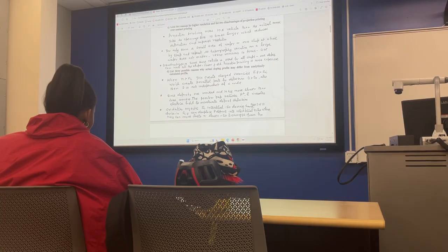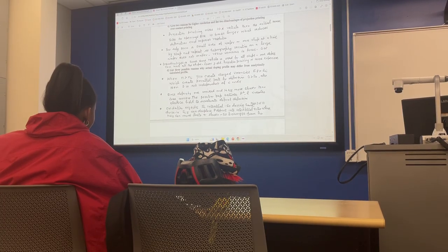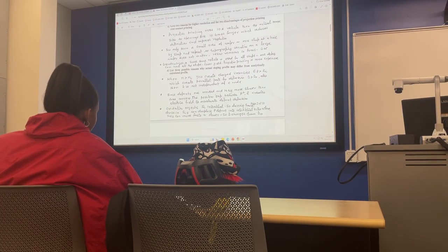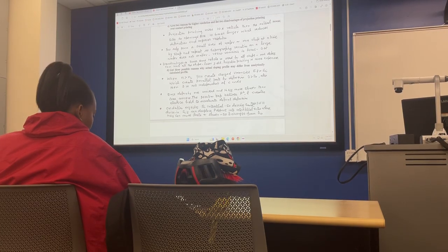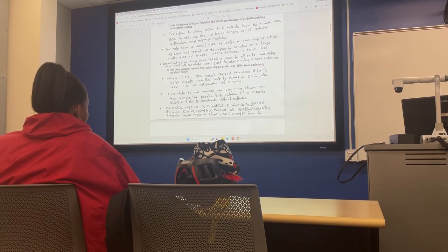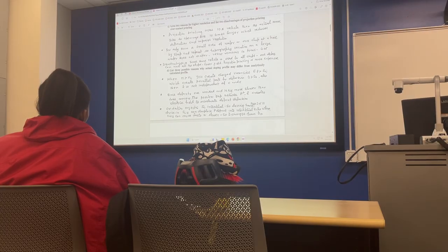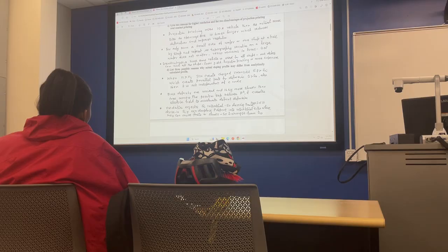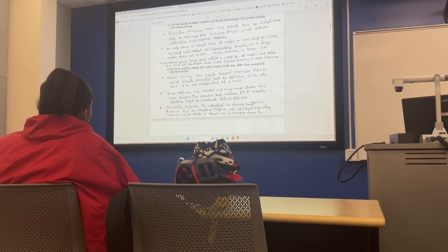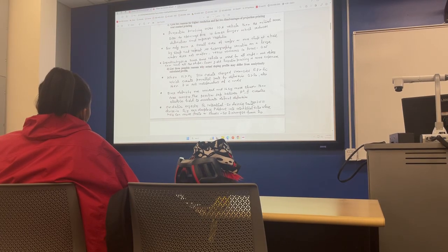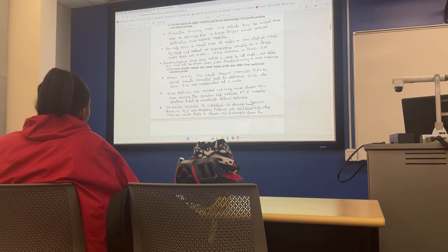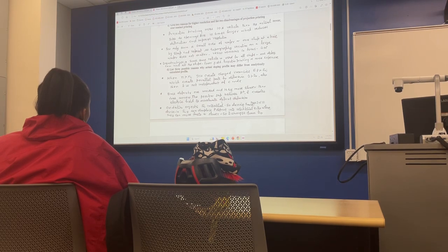Wherever an atom is sitting, it's ionized. Now they both will move, but this guy moves much faster. So this is now a negative electron and you've got a positive ion. There is an extra attraction or a field that drives the ion. This is called field assisted diffusion, because you've got a charged situation here, electrons and phosphorus, as an example, that creates an electric field to accelerate the dopant diffusion.